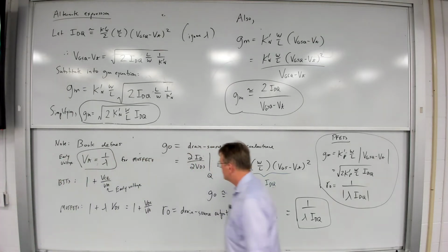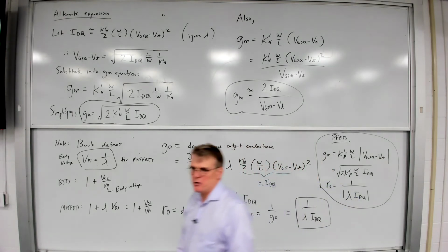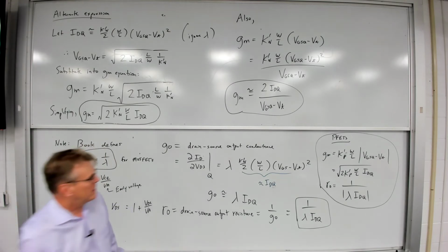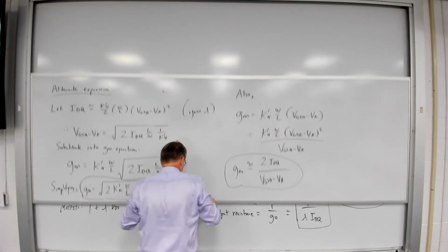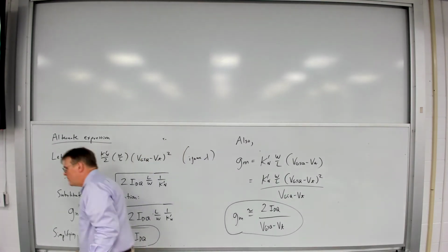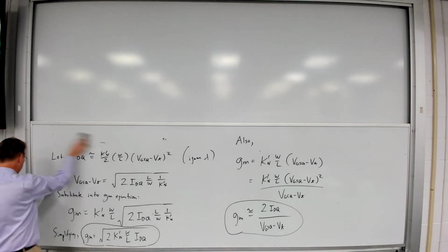All right? So we've gone through and we've derived our equations. Well, what does our model look like? Okay. Let's go ahead and draw our small signal model. Keep in mind, the behavior we're trying to capture with our model is when the MOSFET behaves like a current source. And not surprisingly, that's exactly what our small signal model is going to look like.